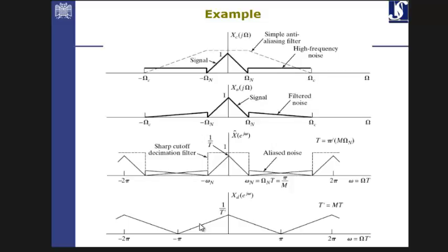Then in the digital domain, when you have the periodicity of this pattern, the consecutive patterns from the repetition of the original pattern overlap each other, and the part that is actually cancelled is the noise part because of the noise shaping. That's the idea of oversampling and noise shaping in more sophisticated A to D samplers.